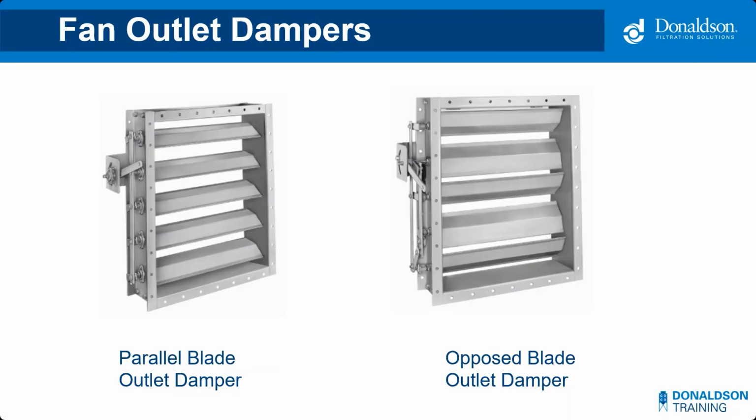An opposed blade outlet damper, the one on the right there, is a bit more expensive because the blades move in opposite directions. It's got some linkage in there that costs a little bit more, but it allows for more control. Specify this type if the customer needs a broader range of control or more even airflow distribution exiting the damper.